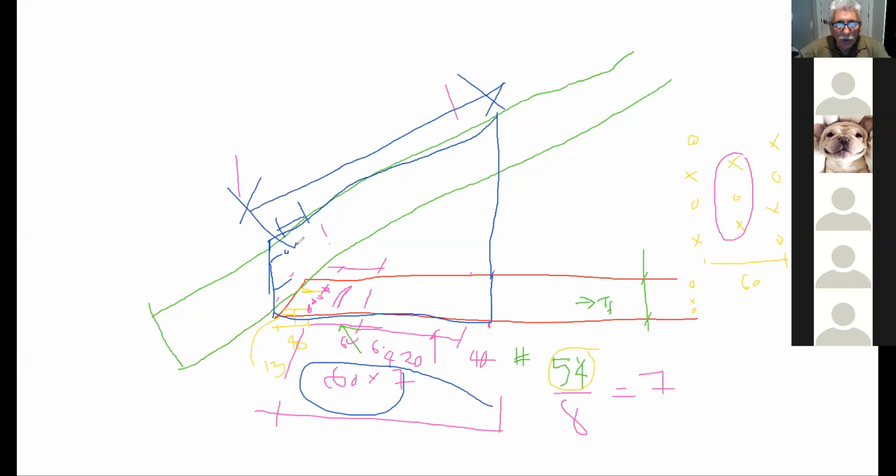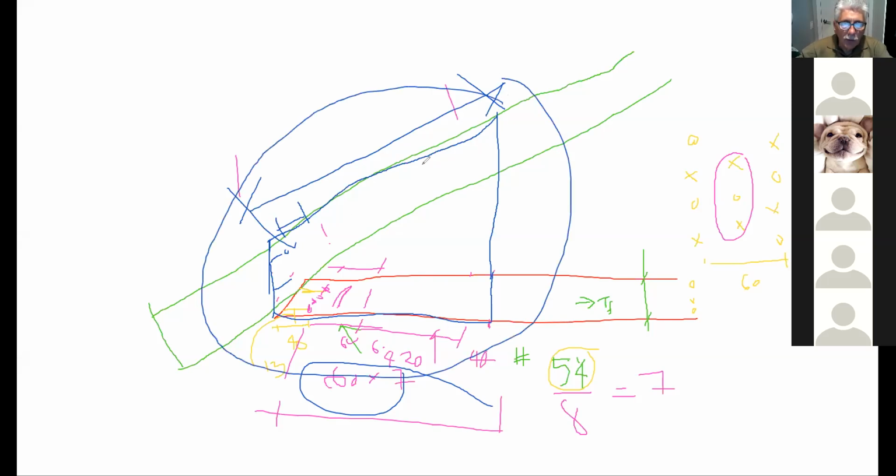So here what the carpenter is going to do, he's just going to take this, divide the spacing. For example, if he knows that he put 7 rows in here, he's going to divide this into 7 equal rows, and he just nailed this. All you have to worry about is that when you specify the size of this gusset plate, when he puts his nails, he can respect all those minimum distances. So you don't have to worry about if this here is shorter than this, and if this is 2x6 and that's 2x6, I know I'm getting ample room to put my 54 nails in there also.